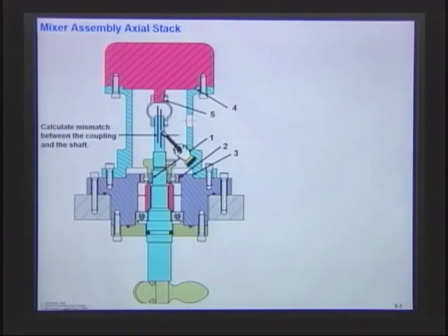But there's other contributing factors. Other contributing factors would be this joint right here. You see where that shaft goes into that bearing right there? That's going to be a contributing factor. And then number two, another one, and I'm labeling them. You would want to do this on your drawings too, or any kind of a stack that you would do, you would label them. And then the next one is where this bearing fits inside of the housing, right? Is there some kind of a joint here?